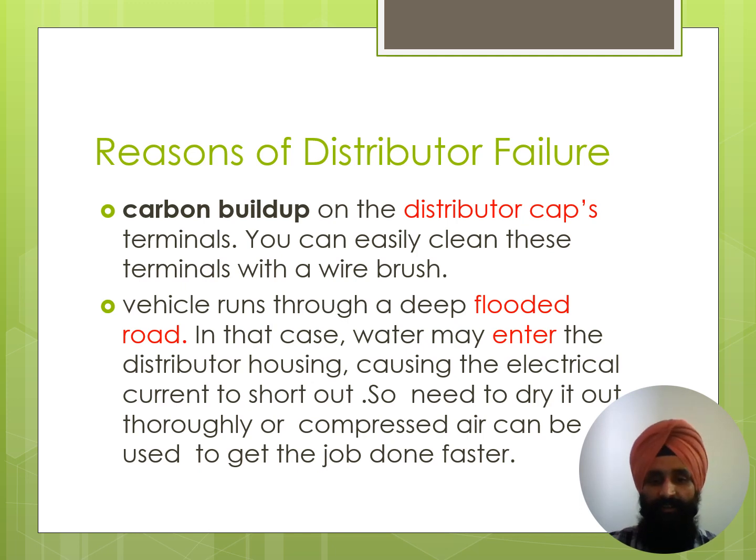So next is distributor failure. Why does this happen? There are several reasons behind it. The first and primary reason is carbon buildup. Carbon buildup on the distributor cap's terminals can be the reason for the distributor's failure. We can easily clean these terminals with a wire brush.